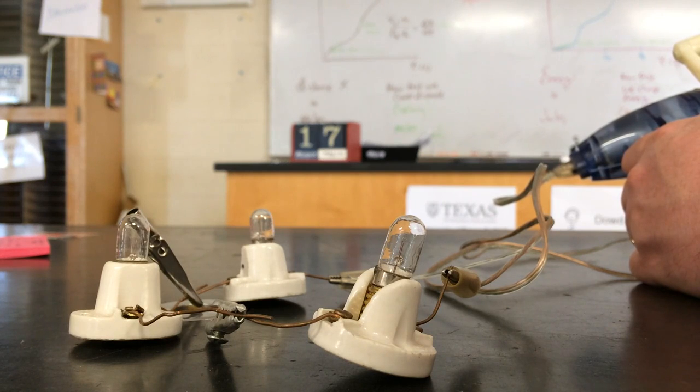And what we're going to see as we look at different devices is that they have a requirement for how fast they need energy. Your toaster, for example, might be a 1200 watt toaster. That means every second it needs 1200 joules of energy in order to supply the heat needed to toast the bread. You could take that energy and spread that out over a longer time by leaving your bread in the sun all day. It would get the same amount of energy, but it wouldn't get it fast enough and it wouldn't be very tasty. The same is going to be true for almost every electric device. So the watts, how quickly it uses energy, are something very important that we'll have to pay attention to.